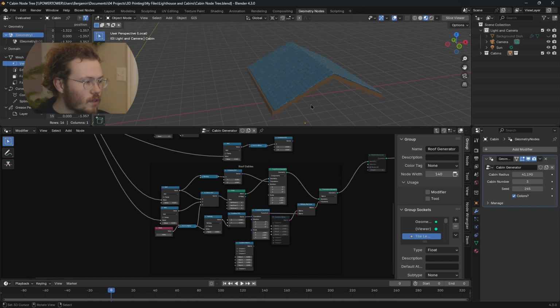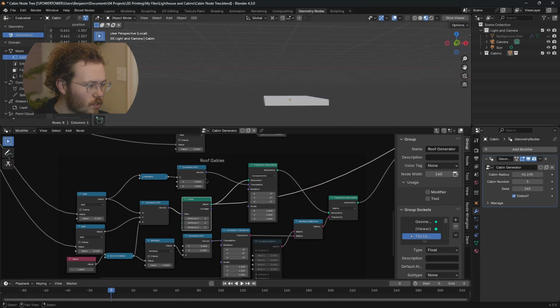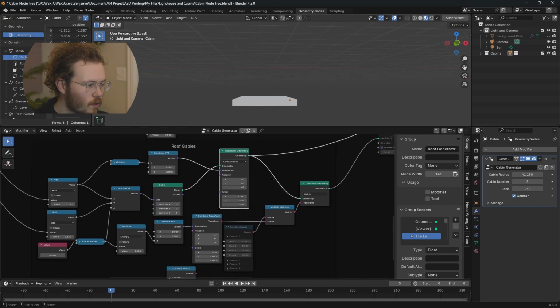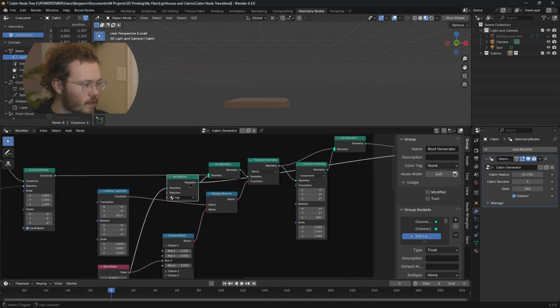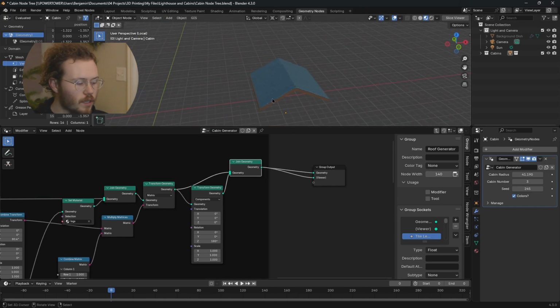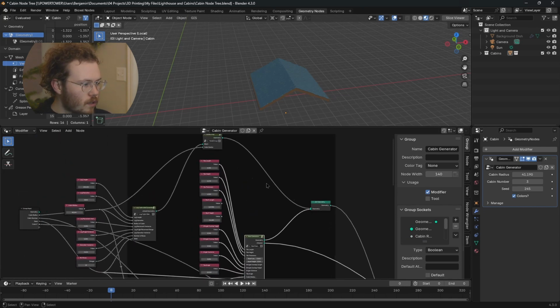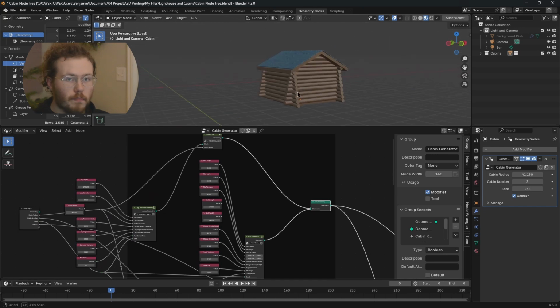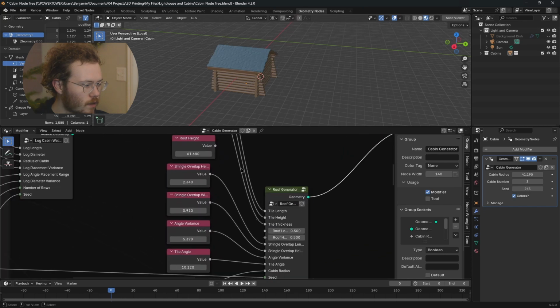So let's back up a second, look at how these gables are. It's pretty simple. Like we've done a lot before. It's a cube. Transform it over, transform it down, so that the top surface of that will line up with the bottom surface of the roof tiles. And then that goes up here, turns brown, it's joined together and skewed. So altogether, pretty slick, straightforward way to put together a parametric roof. So there we have it. The basic, the minimum to make a cabin.